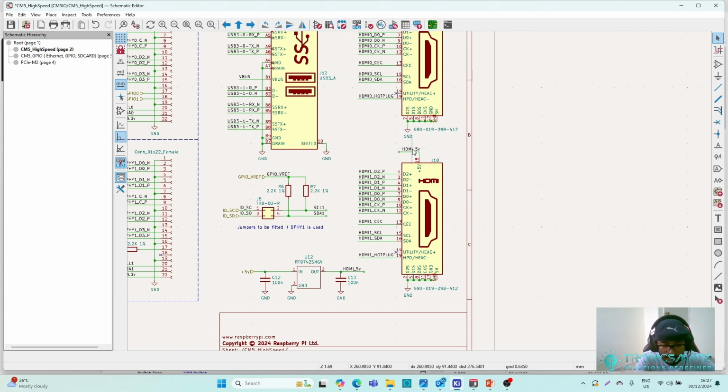By connecting one malfunctioning or one bad device to the board, it is not good that the whole board fails. So it is always good to put this kind of limiting thing. Sometimes we can use resettable fuses or a power limiting switch like this or any kind of protection, like they have done here.